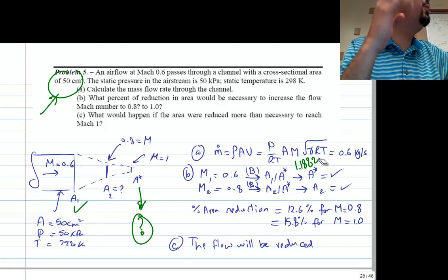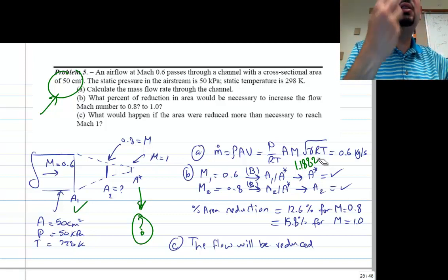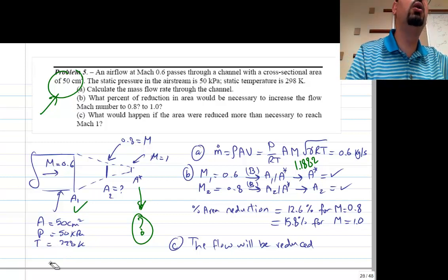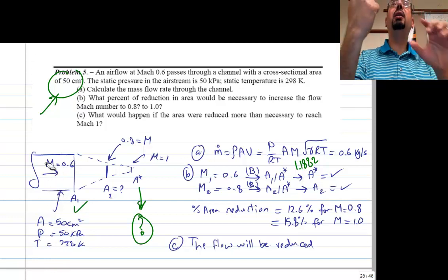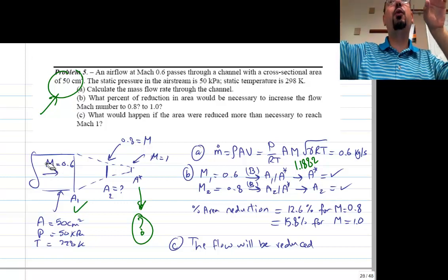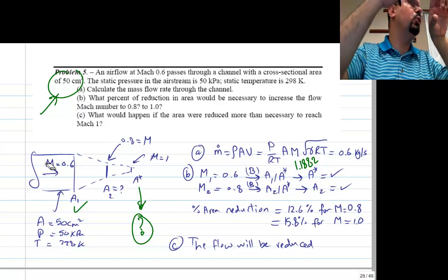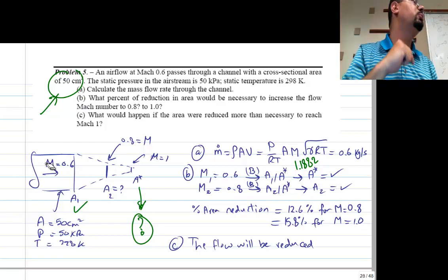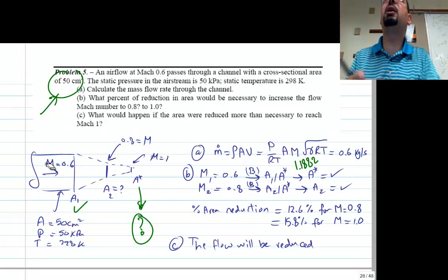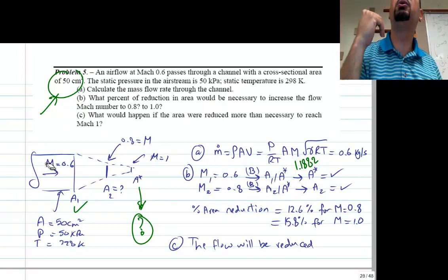this actually works the same way as P total. You don't see P total in this problem, right? But I can ask you, calculate P total for me. What do you do? If I ask calculate the stagnation pressure here, go to the table, you take that Mach number and you get what is P naught over P, whether from the equation or from the table, and you tell me that would be your stagnation pressure. Where is it? Well, if you slow down the air isentropically, we promise you will get that P naught.